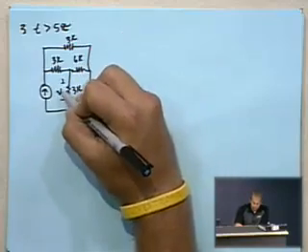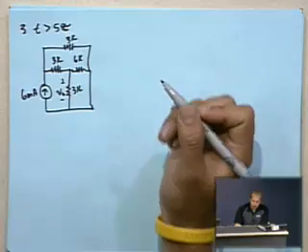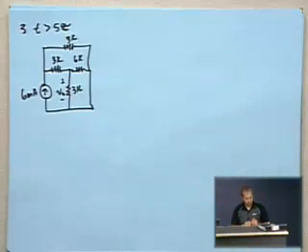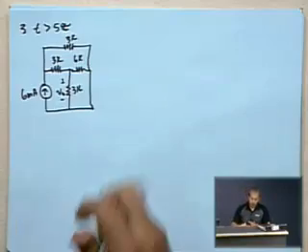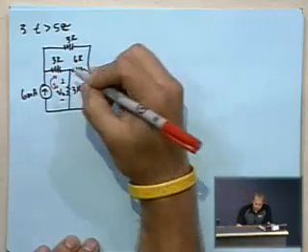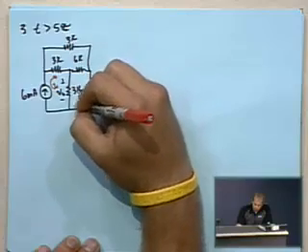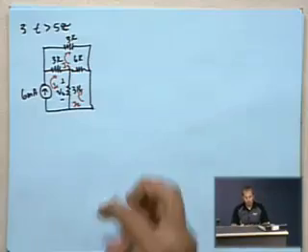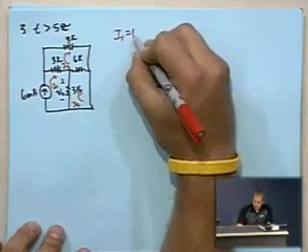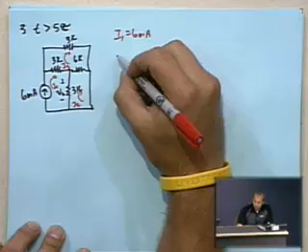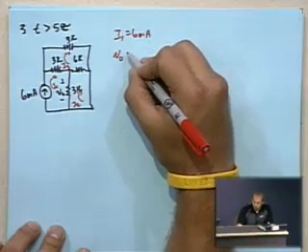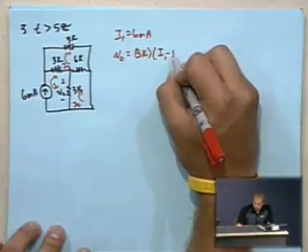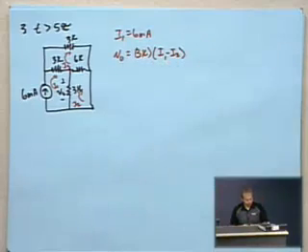We're solving for the voltage V0. I did a mesh analysis to solve for the current running through here: current I1 here, current I2 here, and current I3 here. So I1 just equals 6 milliamps. The voltage V0 that we're looking for will equal 3K times (I1 minus I2) once we solve for those.